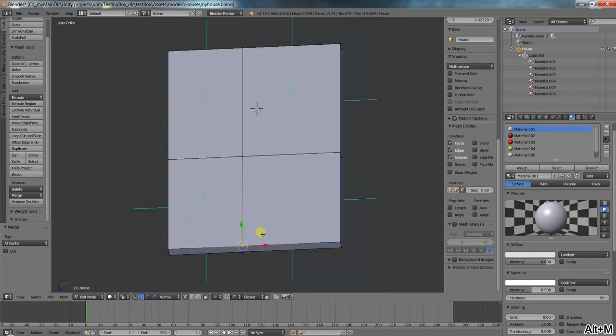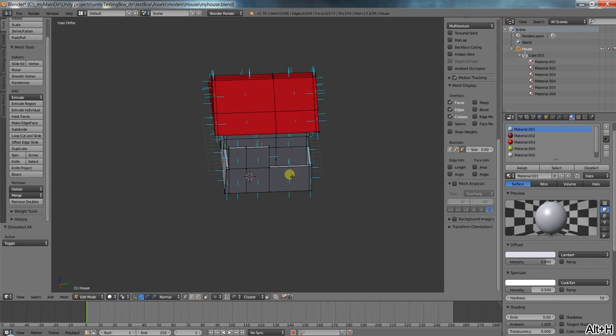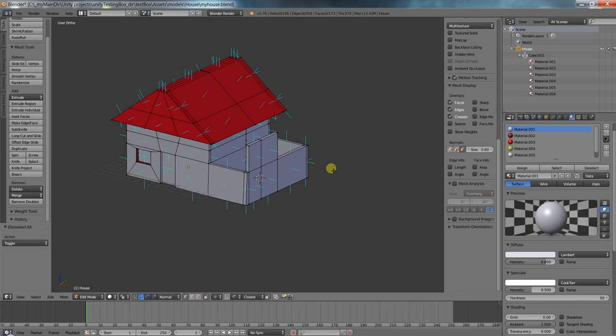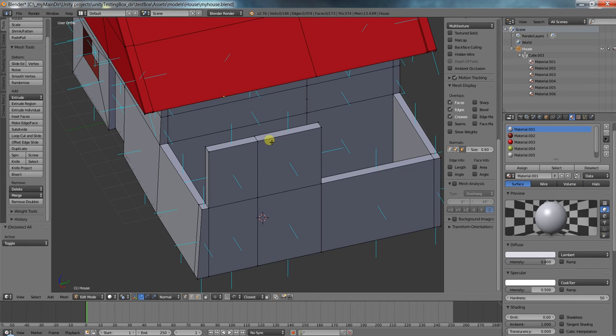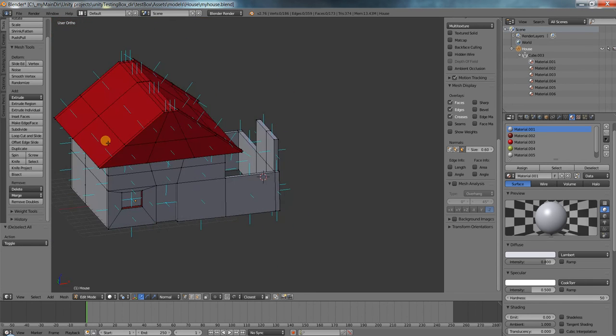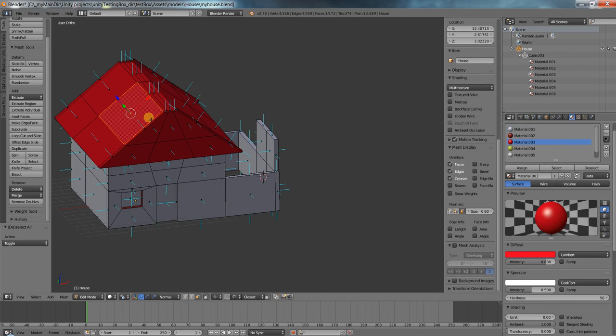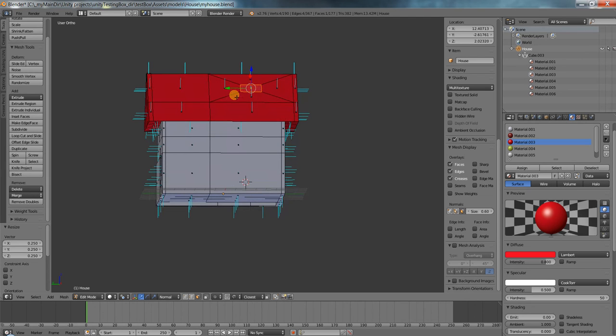Okay, now let's use scaling again for another purpose, and that is to flatten surfaces. So I use scaling to make things bigger or smaller, but you can also use scaling to get vertices so close to each other that they're pretty much the one and the same, and you can say delete double. Or if I wanted to make a chimney, right? First I would extrude and scale to make a coplanar smaller plane.